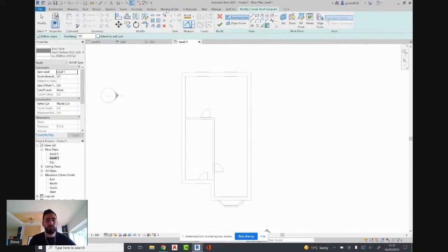And here we have the same. So there's our modify panel again. Some of the components require you to hit this green tick or red X. That means that you need to tell Revit that you're finished the process by clicking the green tick if you're happy, or red X to cancel everything.